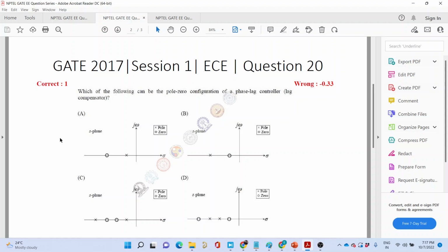So these two poles are in the complex plane, not on the real axis. Say one is closer to the j omega axis, and the other pole is far away from the j omega axis. The pole far away has a much faster decaying factor, e to the power minus zeta omega n, as compared to the oscillations caused by the pole closer to the j omega axis.